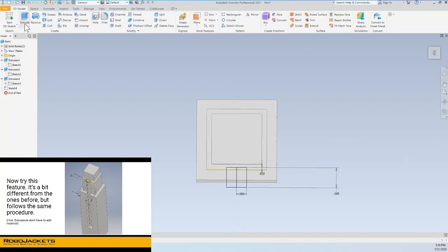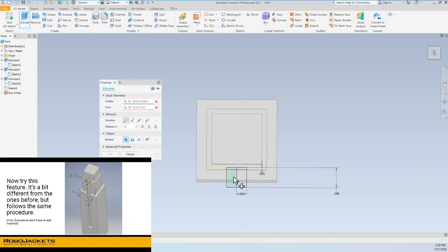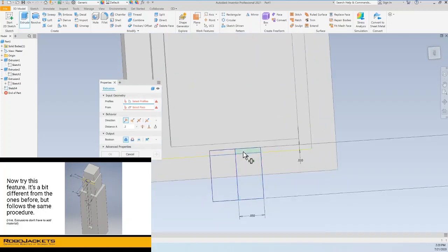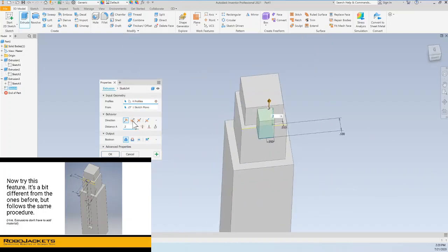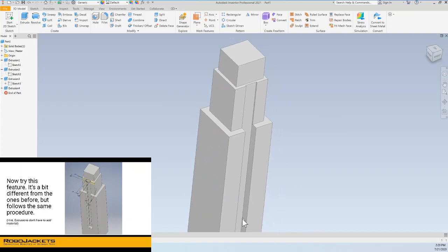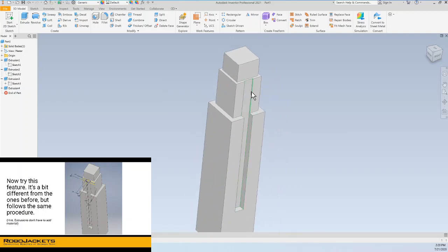all we have to do is finish the sketch, extrude, and then click our shape. We have to make sure we zoom in so we can get all of these boxes here. And instead of going up, we want it to be flipped. And when it flips through geometry, it will automatically become a cut. So we want to make it 1.5 inches. And as you can see, it cuts right through this geometry here.